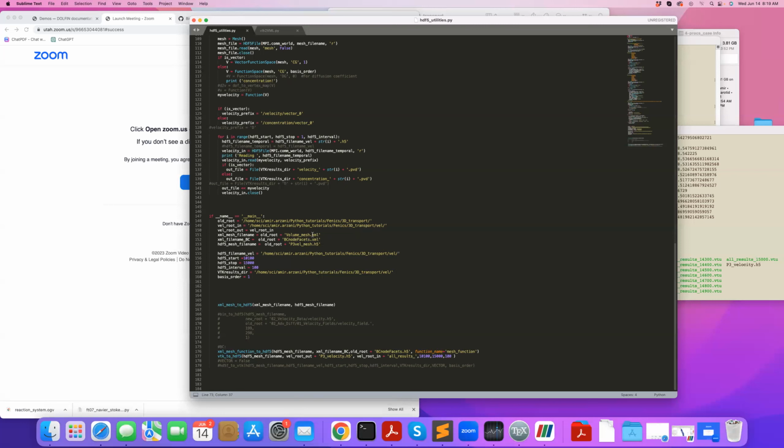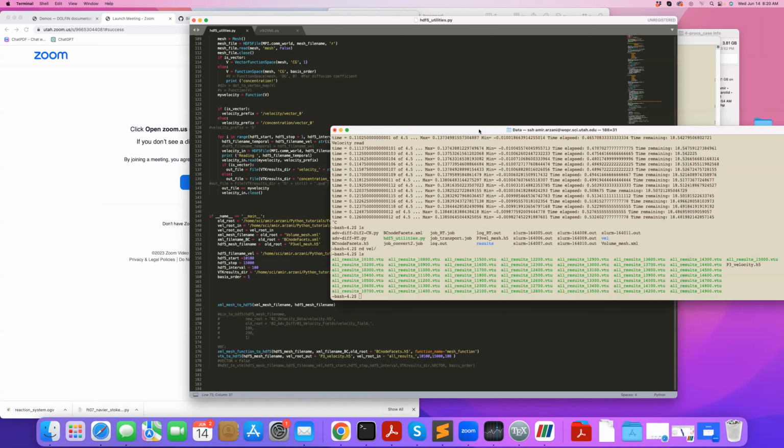You also have the boundary condition tags that you read as input, and you want to convert them to H5. These XML files I showed you in part 1 how you can create. And then your output is written for the mesh as an H5 file, and you also have a boundary condition tag as an H5 file. And then you have your velocities. So you have a series of velocities. This is the index for the first velocity, the last one, and the interval between them. So something that looks like this.